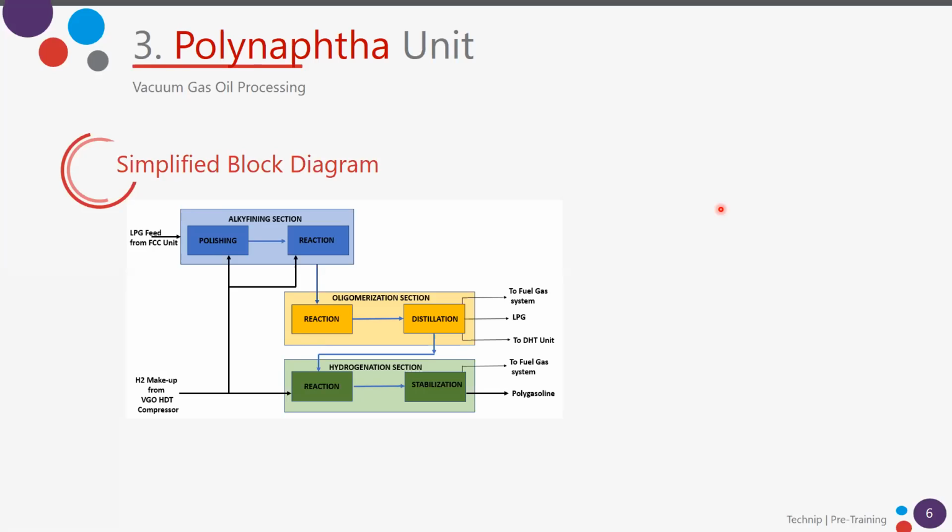Sorry, Bella, I have a question. Well, about the percentage of the olefin. Yes, it's undesirable, right? So why don't we reduce it at the product? If we raise the ratio of the hydrogen, we will decrease the ratio of olefin in the product, right? If you say, why don't we reduce it in the oligomerization section, and we avoid this hydrogenation section?